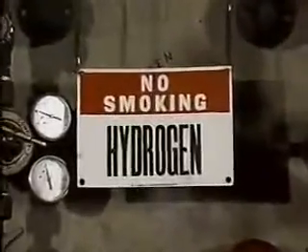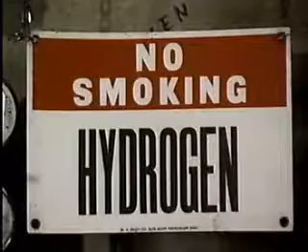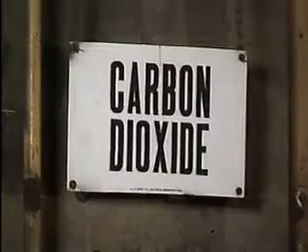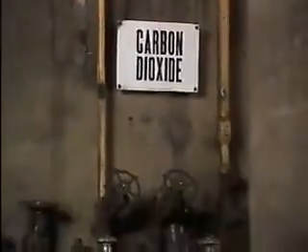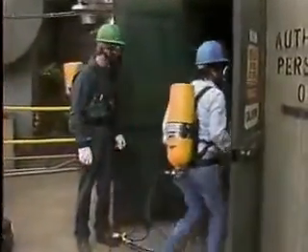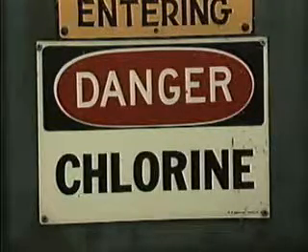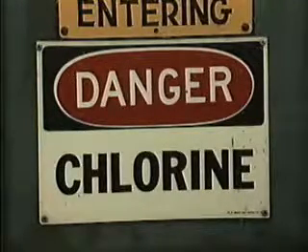Some compressed gases, such as hydrogen, may be flammable or explosive. So open flames in spark-producing equipment should never be used around these systems. Some compressed gas systems may contain gases that are toxic, and some may contain gases that displace air. In either case, these systems may make surrounding areas unsafe to breathe in if a leak occurs. Plant procedures may require the use of a respirator by anyone working around such systems. Harmful gases present in compressed gas systems are usually identified by warning signs, which alert personnel that a hazardous gas is used in the area.